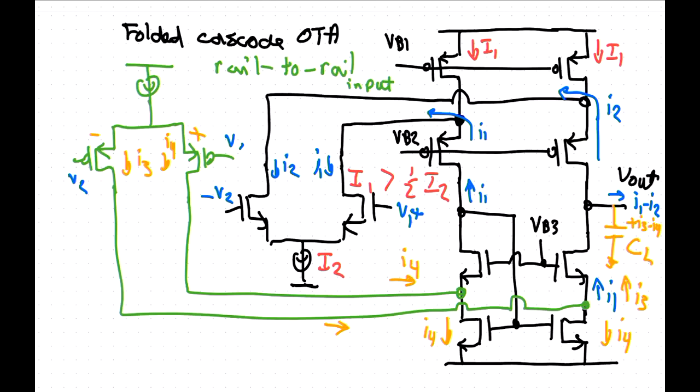And the voltage you need to have here is an effective voltage, or the absolute value of the effective voltage. The drain has to be lower than the source by, let's say, for the sake of argument, 100 millivolts. It's a bit low, but let's just say that. So you're not allowed to let the drain be higher than the gate by more than a threshold voltage for it to be in saturation. That's another way that you can write it.